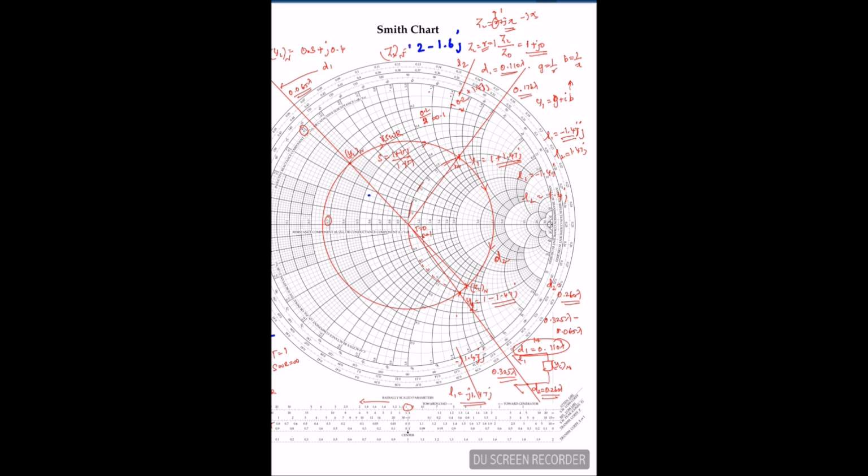What I have to do is, from L1, which is an impedance in the Z chart, rotate 180 degrees again. Remember this step, keep it in mind. From the L1 of whatever wavelength I got, this is my point. So I have to draw one more straight line here.